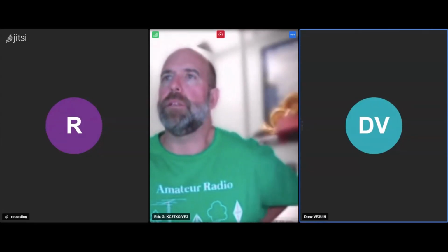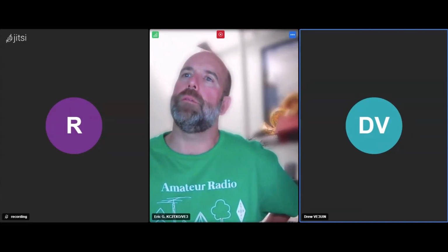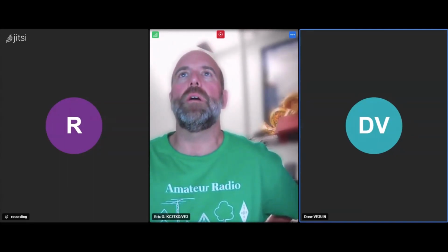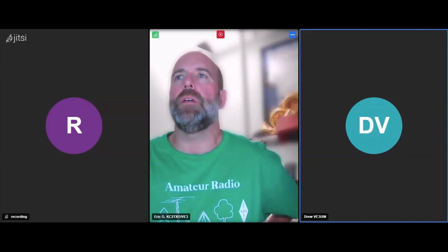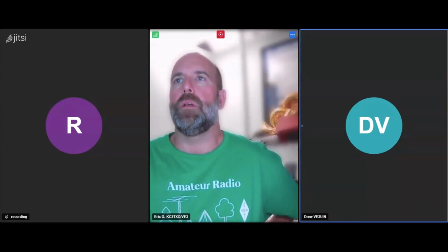Right. That's what this one's built for. I just printed it out because it was kind of close to what it fits for me. Right. And so I wanted to build a 9-to-1 because there's another thing you can make with a 9-to-1, and it's called a terminated end-fed dipole.